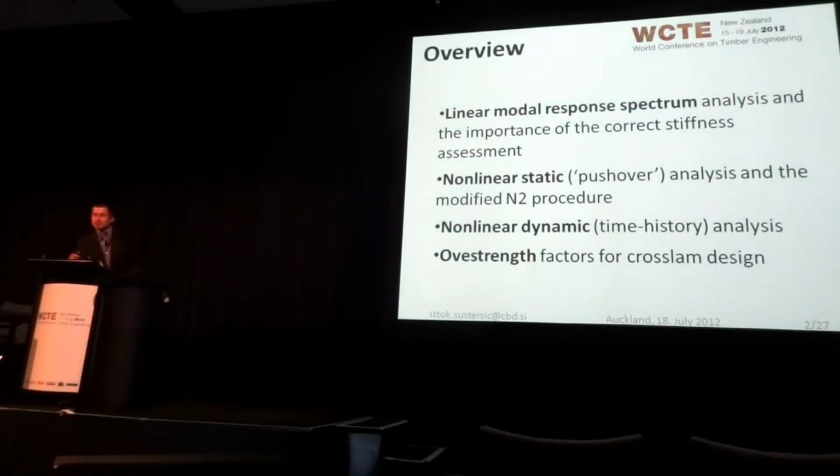We shall basically go through the methods that current codes and standards offer to a designing engineer who is dealing with seismic design. So basically it's going to be a linear model response spectrum analysis, and I shall try to show you the importance of the correct stiffness assessment, as Robert has just pointed out. Then we shall move to the nonlinear static, or so-called pushover analysis, with the modified N2 procedure. N2 is the displacement-based design method incorporated into Eurocode for the last 8 years. Then we shall move to the nonlinear dynamic time history analysis, and in the end I shall try to tell you something about the overstrength factors, which should be used when dealing with cross-lam.